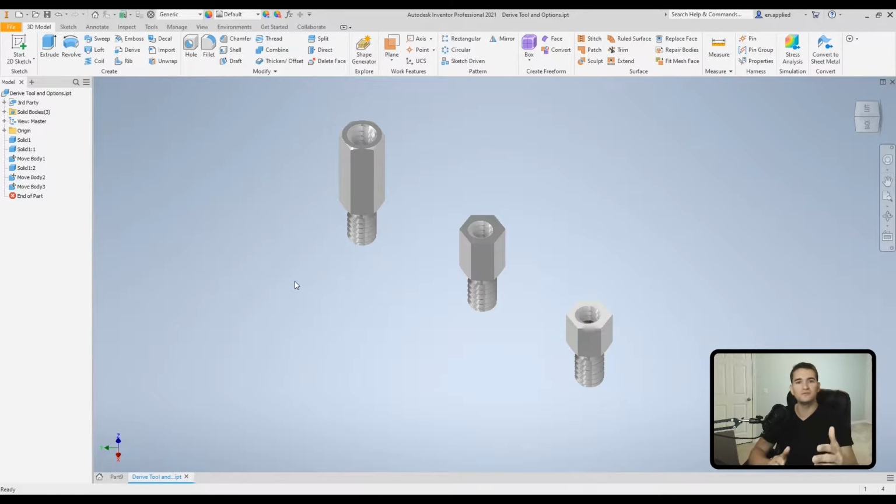And the whole objective of this practical example is to simulate a scenario in which it's less expensive in our design to take an off-the-shelf piece of hardware, so in this example, it's a threaded standoff, and then grind the height of this top portion down to suit our design needs in our particular assemblies that we're putting together. So these are actually part of this original part, but this is a simulated scenario in which we cut this height down to 1/4 of an inch here, and then 3/16 to accommodate our various designs.